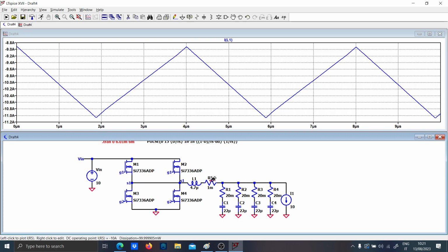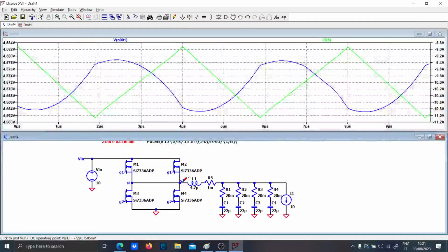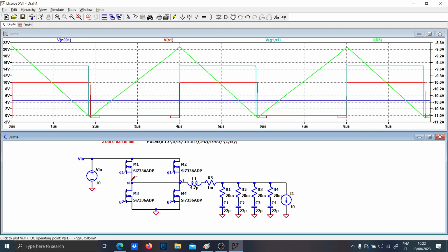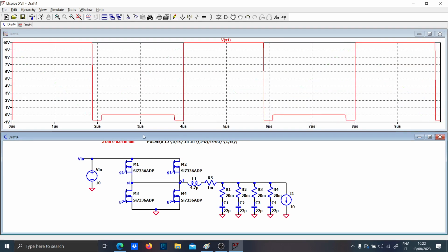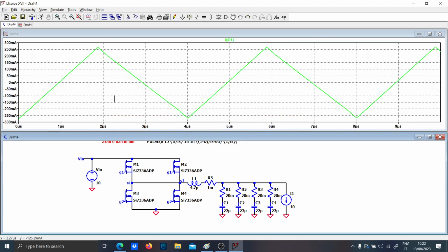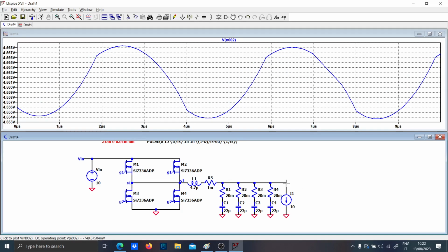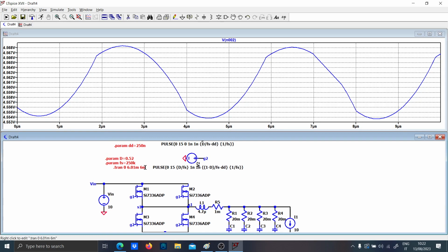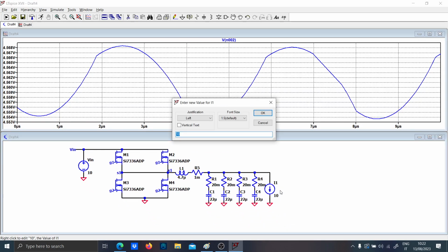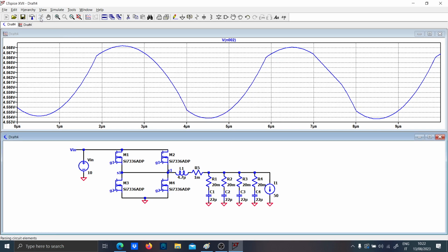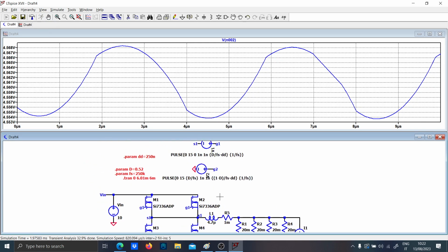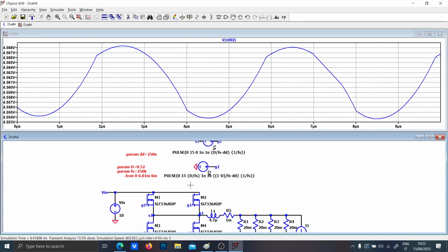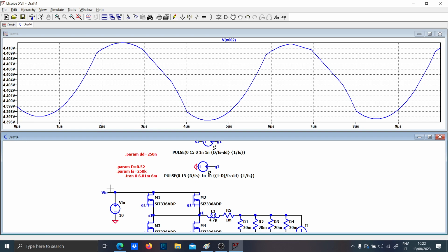The inductor current shows it is working in CCM. This is very good. Okay, the time waveform is switching between 0 and Vin. This is correct. And the current which is flowing into the capacitor is even correct. I think that if I increase the current to 50 amps, I will have to increase the transient a bit, but apart from this, no. So 60 milli is enough.